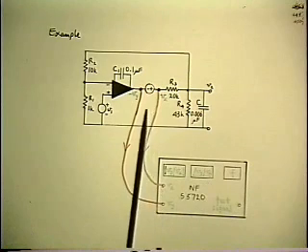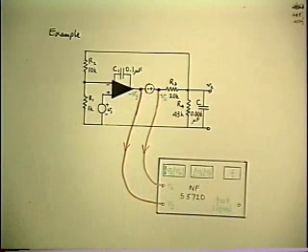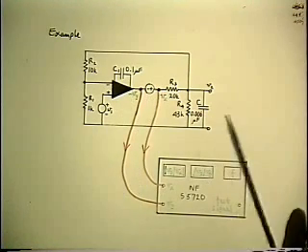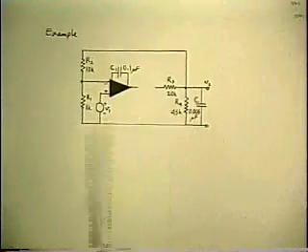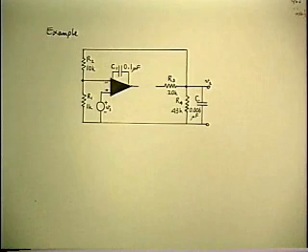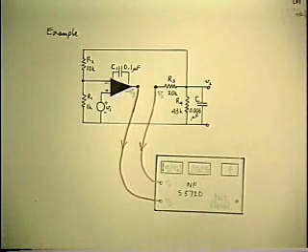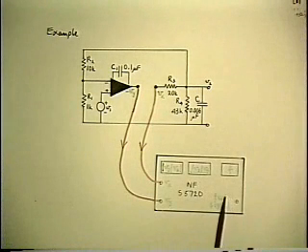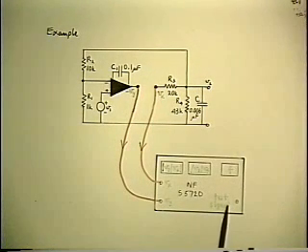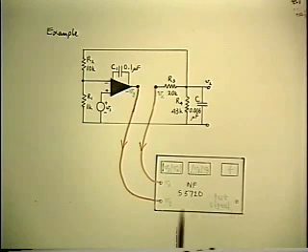Now, the remaining part of it is how do we get the injected voltage? So what we need is a floating source. So I'll put the analyzer back again. But the test signal output is usually grounded. Even if it's nominally floating, of course, it actually has a lot of capacitance to ground, so it's not very convenient.